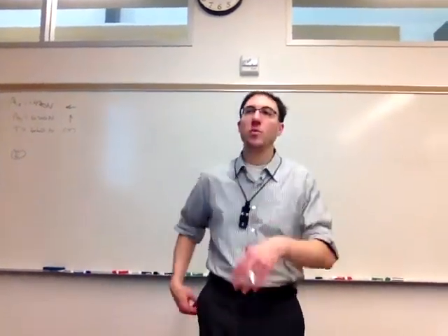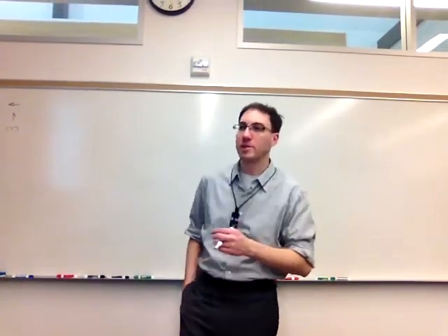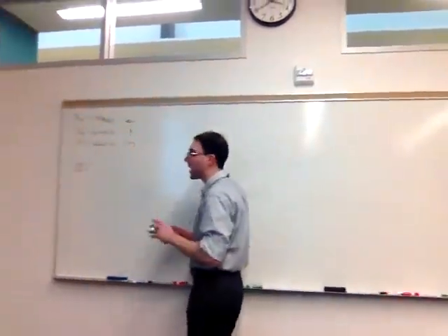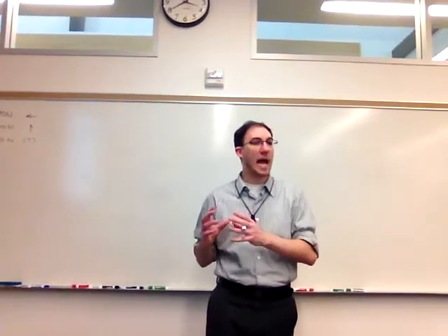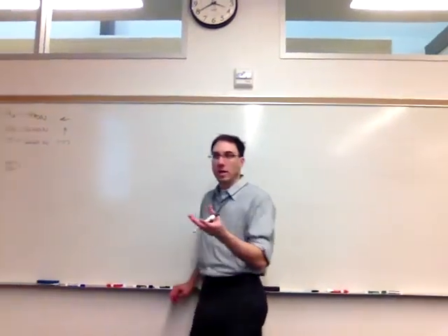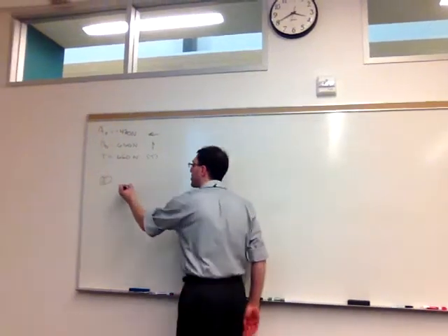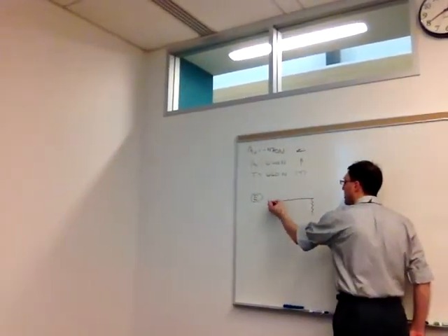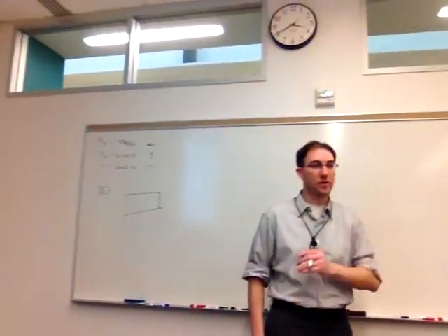The method we take is we'll make a vertical cut through the beam, or a cut transverse to the beam that crosses through E, and we have the option of taking everything to one side of the cut or the other side of the cut and copying it exactly from the original picture. It looks like there is less going on to the left of the cut at E, so I'm going to choose to model that, although our answer will be the same whether we took the left side or the right side.